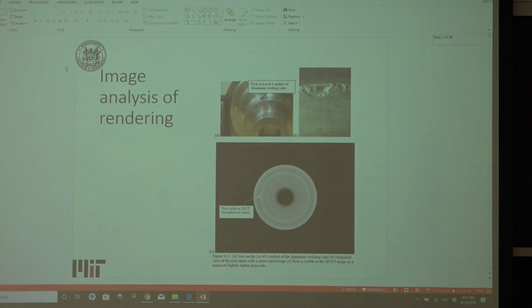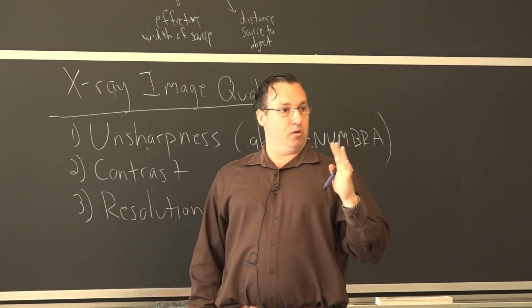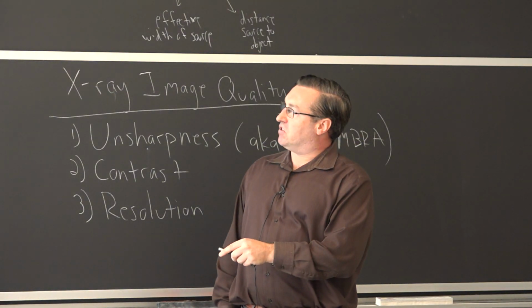So the sample I handed out, I'm not sure if any of you saw, but on the sample itself, there's a dent in this area here. So this is just a close-up of that. You can see that the system was able to distinguish between that versus the flat bottom holes and the side drilled holes. So that's just an order of magnitude on the resolution you can get for that CT system, and that's a product of the microfocal spot size. If you were doing film radiography, you probably would not be able to distinguish that at this sensitivity.